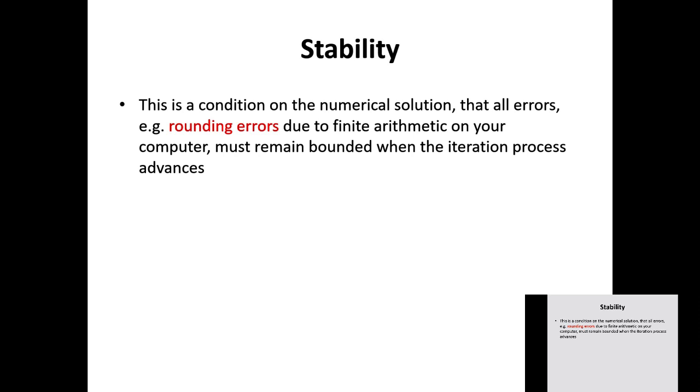So it's better to stop there than there, because all you are doing here is doing it again and again. You can introduce a numerical error into this if you iterate too much, because it's all an approximation. You can increase your error if you iterate for too long. Once it's converged, once you've got a good converged solution, you stop there.